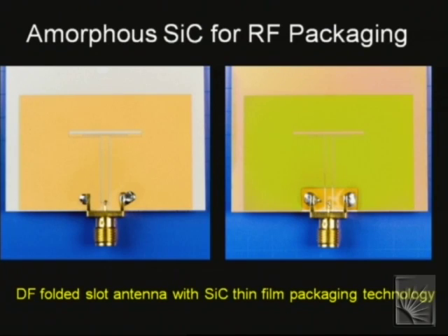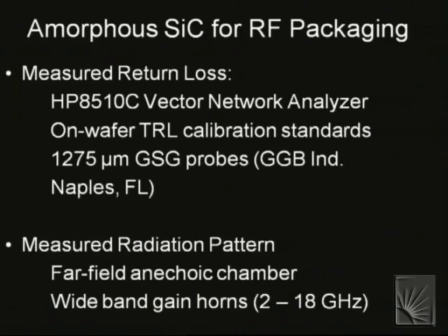We didn't go right to the polymer substrates, as you might imagine, for making implant devices, because in fact NASA wasn't in the business of making implant devices. Instead, they had readily available these antennas fabricated on alumina substrates. So the conductor's made of gold, alumina substrate. This is an uncoated antenna, and this is one coated with silicon carbide. The connector area here was left uncoated because we worried that there actually might be delamination over those large features.